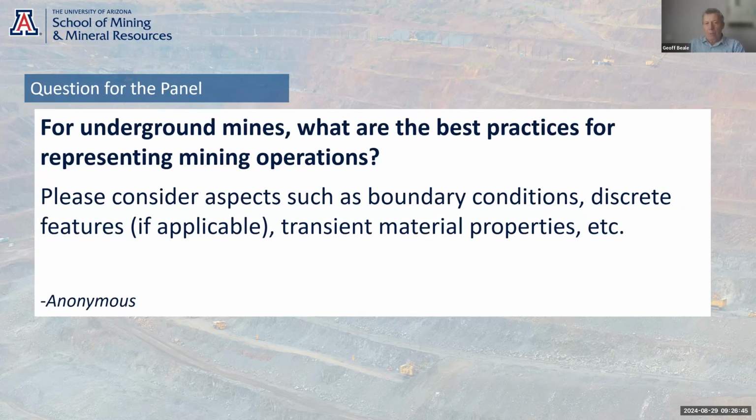So before anybody else jumps in, I'll mention the perils of exploration drill holes, which are typically good for open pits because they help depressurize the slope, but bad for underground because they bring water down to the workings. I mean, once you get to 1,000 meters or even 500 meters, the rock gets quite tight. So it is often the exploration holes which give you the problems.